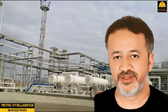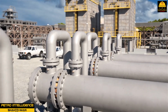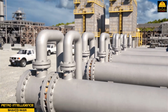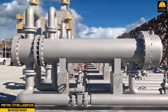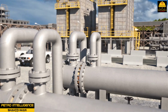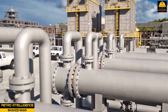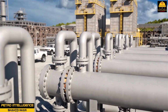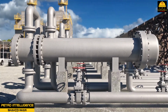Designs and components. Exchanger nomenclature uses the terms front end, shell or middle section, and rear end to refer to the three parts of shell and tube heat exchangers. The front-end design of a heat exchanger varies depending on the type of service in which it will be used. The shell has 7 popular designs that are linked to the way flow moves through the shell. The rear-end section of a heat exchanger is linked to the front-end design. Industrial manufacturers are currently using over 9 popular designs.